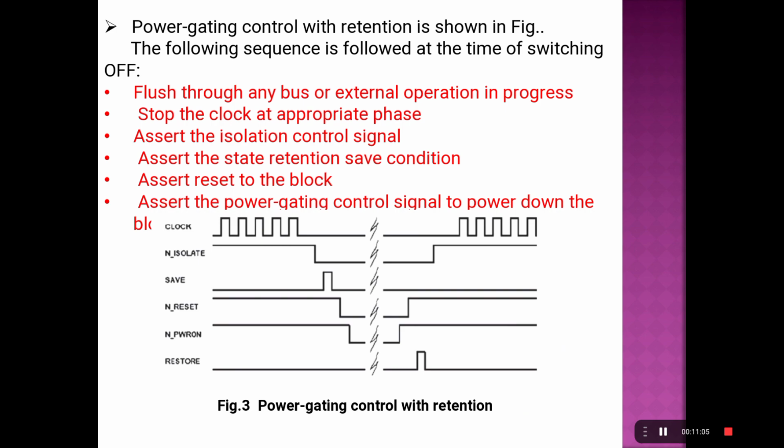Suppose you want to save the data present in the corresponding register. This is the scenario. Before asserting the reset signal, you have to apply one save signal, as well as one restore signal at the end. Okay, so that is the procedure for this.